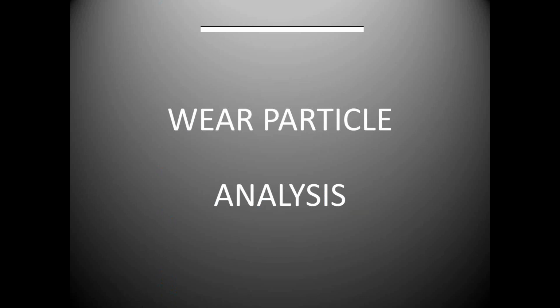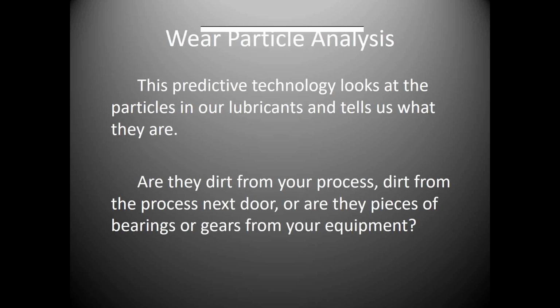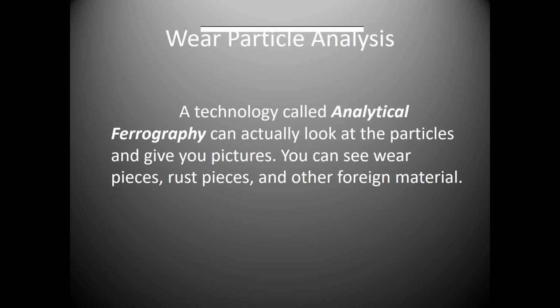Now we've looked at the predictive technology of oil analysis, but sometimes we may want to see what the particles look like. We want to know what the particles may be. Are they pieces of bearings or gears? Are they dirt from the process next door? Are they dirt from your process? This wear particle analysis is going to give us that information.